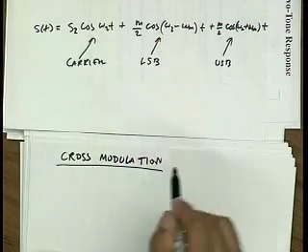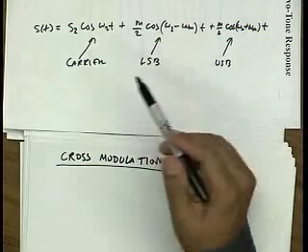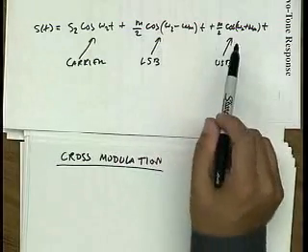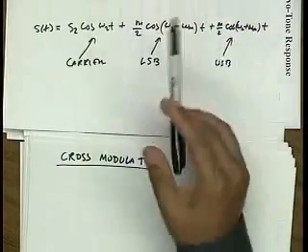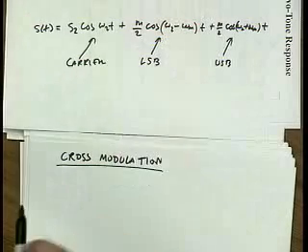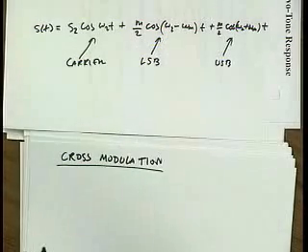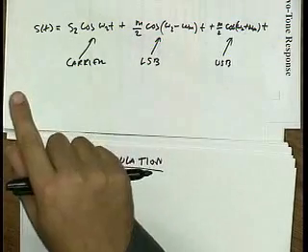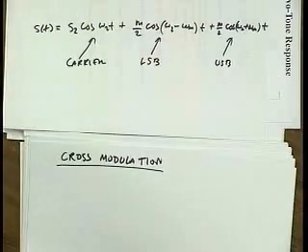And the idea of cross modulation, of course this was observed experimentally, is that you have two channels. They're both amplitude modulated. You go through a nonlinearity, and then all of a sudden one channel contains a copy of the modulation from the other channel.